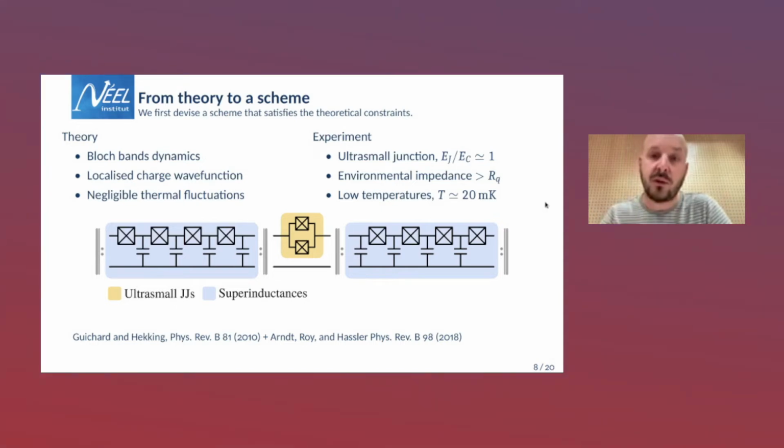If you put a very large resistance in series with your tunnel junction, it will be difficult for the charge to tunnel, so you have something like a Coulomb blockade, if you wish. Again, it's hand waving, but it's kind of Coulomb blockade. So you can tunnel charges only one by one. So this is the hand-waving argument why you need very high impedance.